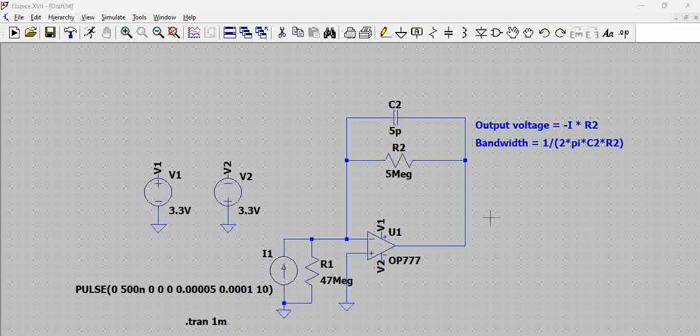Now there are a few things which we need to do before working on this particular circuit or confirming the circuit, or we can say some design steps involved. What are those? So the first thing, you see a resistor here. This particular resistor is actually required, especially at the startup of this particular op amp, such that there is a stable voltage here. Okay, that is a primary requirement.